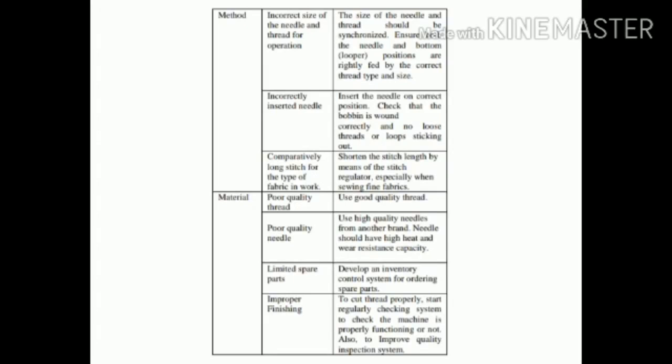Cause: comparatively long stitch for the type of fabric and work. Solution: shorten the stitch length by means of the stitch regulator, especially when sewing fine fabric.